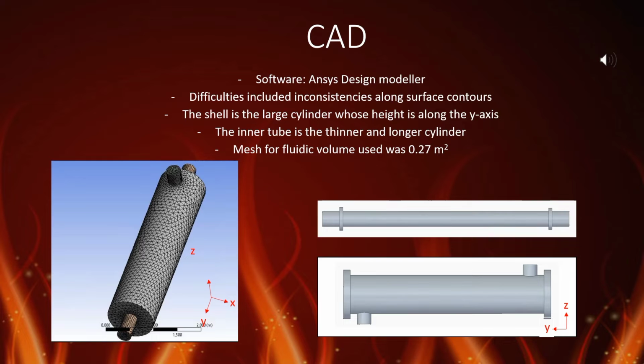Steel is also cheaper to use for the shell material since this part of the exchanger has the most surface area. Copper is an ideal material to controllably conduct heat from the hot fluid to the cold fluid due to its high thermal conductivity. In retrospect, we have learned that a good simulation hinges upon a well-generated computer-aided model, as well as a good understanding of heat transfer by conduction and convection between materials of different thermal and flow properties.